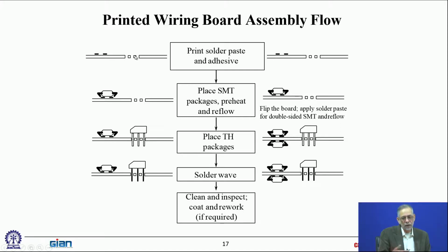Well, in low volume processes, you may actually dispense with a dispense head. You will go bump pad by pad. They're usually computer programs, so it goes pretty fast. Pad by pad, it goes through the whole circuit card and puts down the right amount of solder paste, metered, right amount of solder paste on every pad. For high volume, you don't do that.